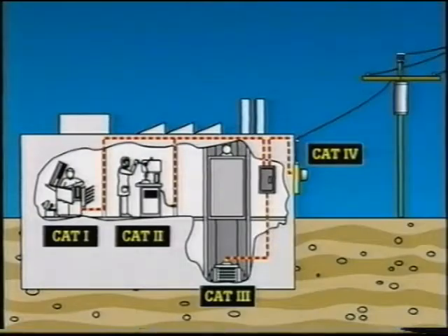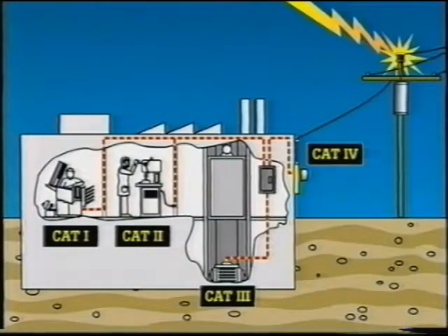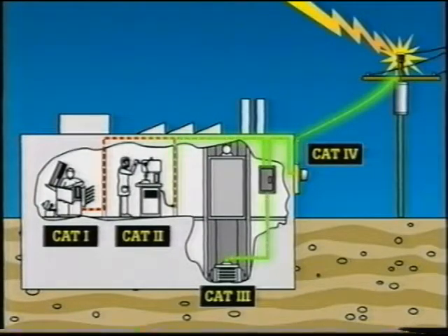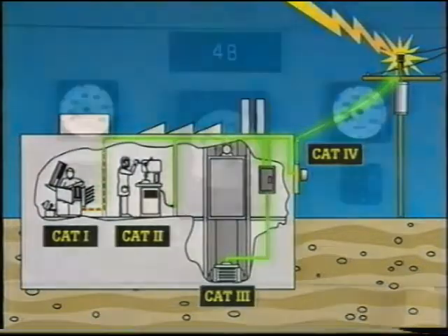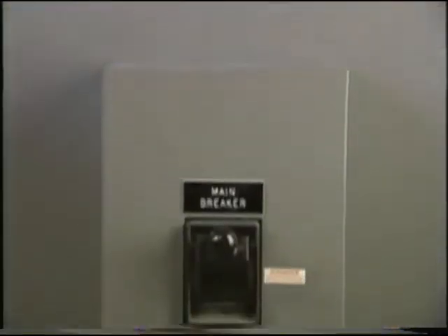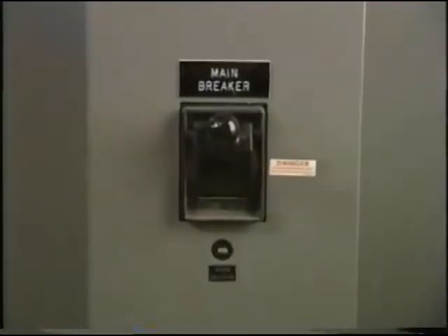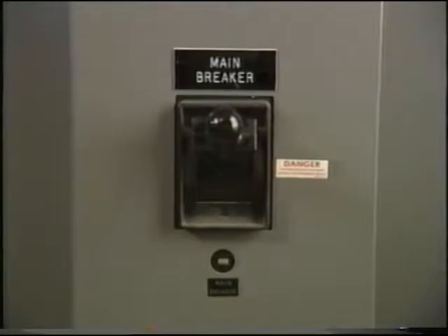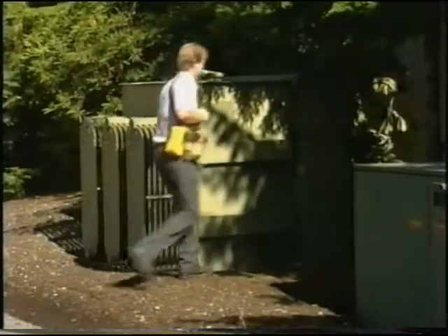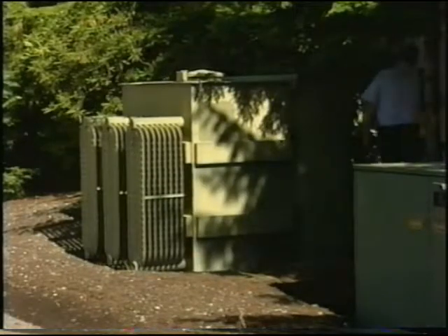Transients are not as dangerous in lower categories because lightning or other high-power transients will be dampened as they travel through the cabling and equipment in a building. Remember, in general, the greater the short-circuit current available, the higher the Cat number, and the more hazardous the transient. Cat 4 is associated with the origin of installation.